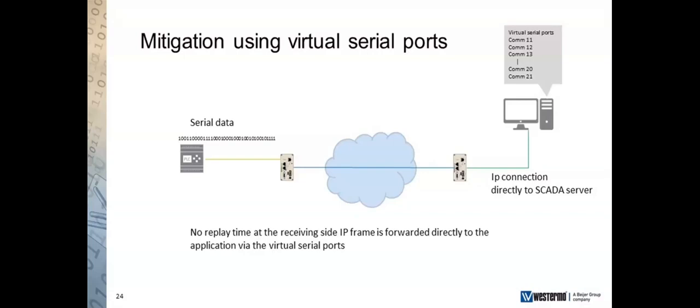In the good old days, you would probably have lots of serial to IP converters, like terminal servers sitting in racks, 19-inch racks in the computer room. And the SCADA will be selecting a serial port to communicate over and then talk down to the remote site and then gather the data and get the messages back and forwards. Very quick tick-tock. Still limited to actually using a serial port at both ends.